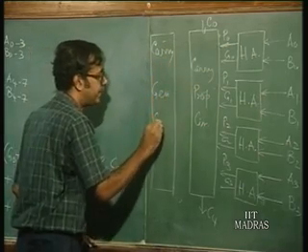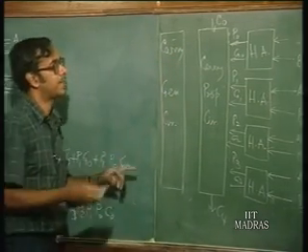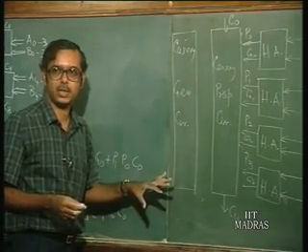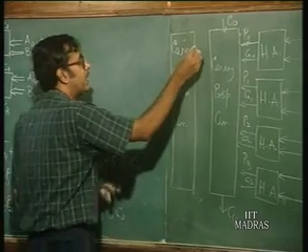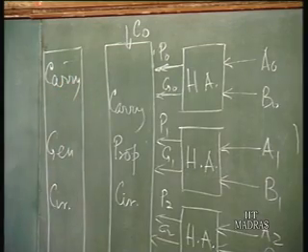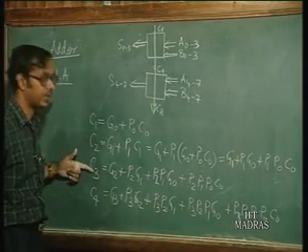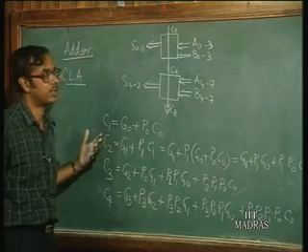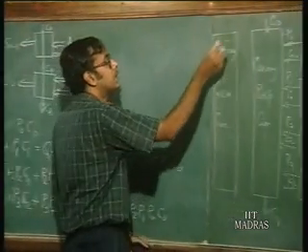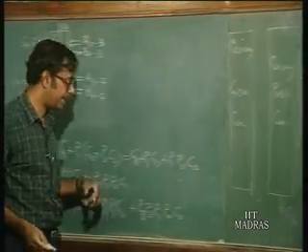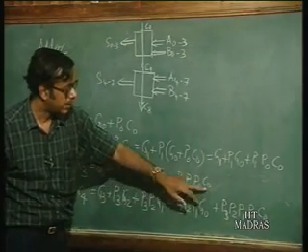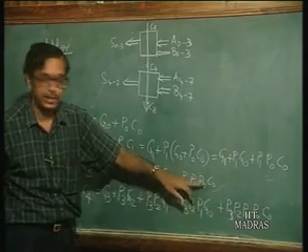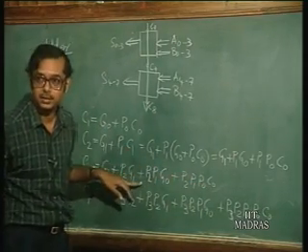Okay. So, this basically generates the carries for the different bits in this 4-bit carry look ahead adder. You are going to generate the carries C1, C2, C3, as well as of course, you require C naught also. So, this requires as inputs C naught and the different P's and G's, up to that stage.